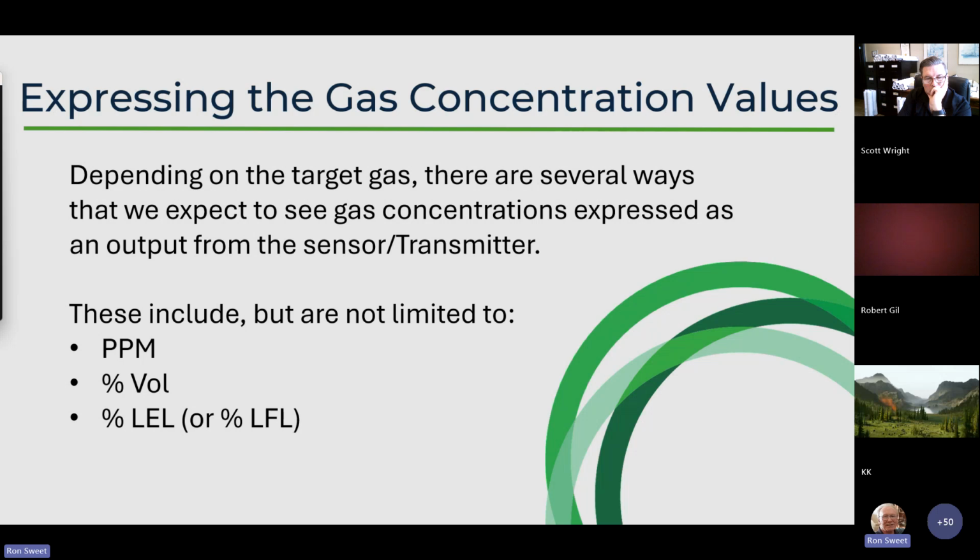It is that pool, that buildup of hydrogen gas that we want to monitor. We do not want that pool to reach the concentration of 4% by volume or 40,000 ppm. That is the lower explosive limit or lower flammable limit for hydrogen gas. So typically we would bring on the ventilation at 10% of that lower explosive limit or lower flammable limit. So at 4,000 ppm, we would be bringing on the ventilation.